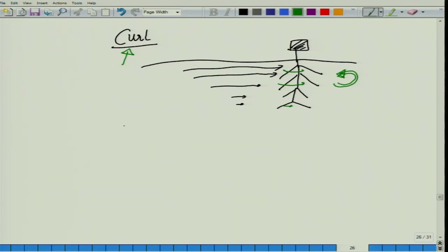And mathematically the definition of curl is that I take the vector field. So, let us say that vector field happens to be H, and then I evaluate this H over the closed line integral. And after evaluating that, I divide this by the surface, that would be the open surface that I have. So imagine that this is the closed line integral or the contour that I am imagining, and this is the total area.